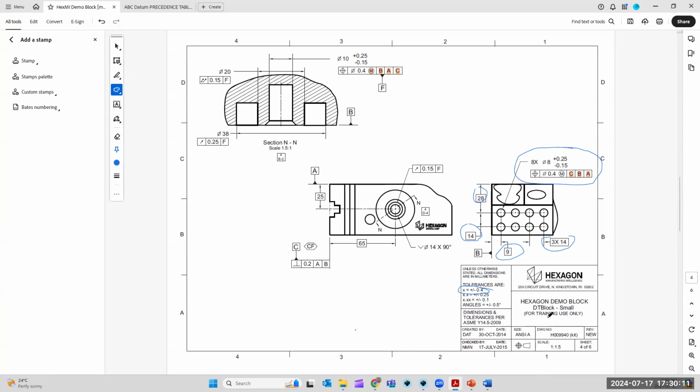No, sir. In basic dimension, absolutely not. No tolerances apply. So do not mistake that and use the 0.4 tolerance on basic dimensions. If there's a basic dimension, it's because this number, this number, this number, and this number are constrained by some sort of GD&T.